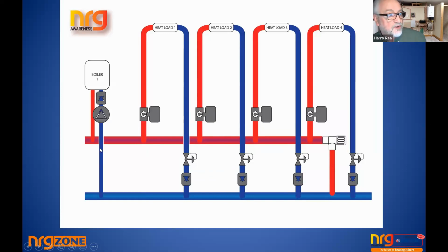But the point I take away from this is the water has to get back to the boiler, and this system, even though it has an automatic bypass valve, the water has to fight past that bypass valve to get back to turn off the stat, or to give the boiler information that the system is up to temperature.